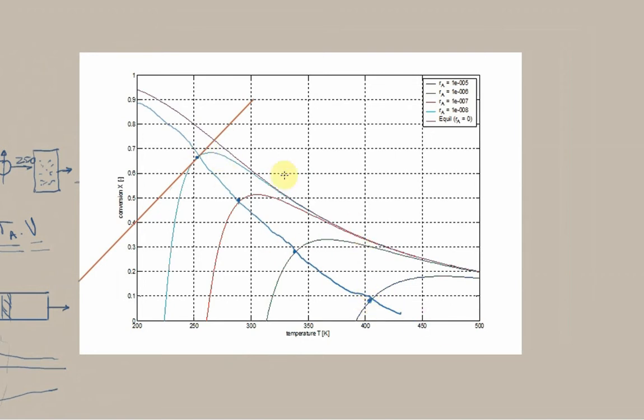So we can say we've got a very undesirable region here. This equilibrium line is where the reaction rate is 0, so we definitely don't want to be there. On the other hand, we've also identified this highly desirable region where we can maximize the reaction rate. And so we now want to design our CSTR to accomplish these nice small reactors.